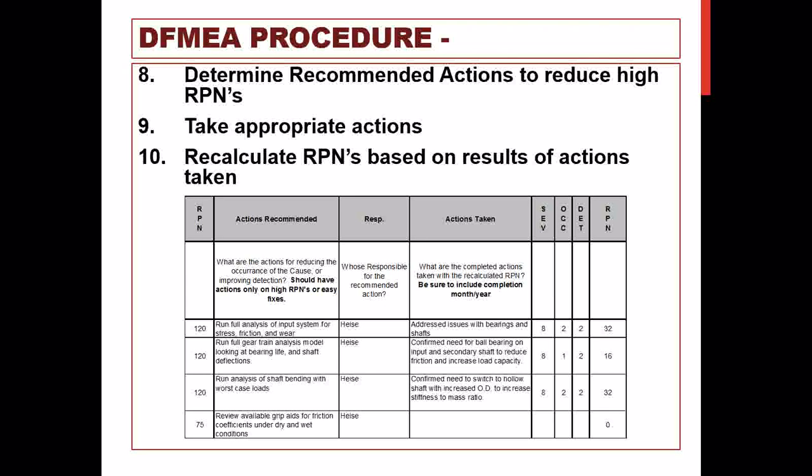And so on down, if you look through the rest of the rankings, we're looking at bearing failure overstress, or shaft bending overstress. We've got life testing and design analysis, again 5s and 3s. You'll notice that in all of those where the system can't operate due to loss of function, those are ranked as 8s. And when we get down to the foot pedal slips, or the foot slips off the pedal, we can't operate the system comfortably.